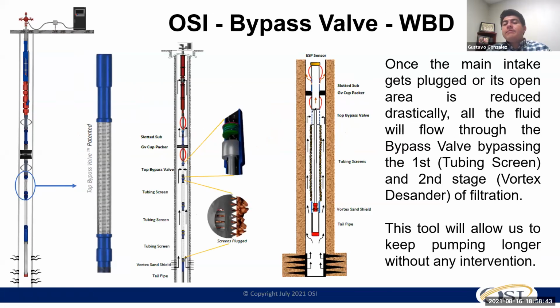So going back, it's worth selecting the sand screen as a method, as I mentioned previously. There is always that concern that filters or the screens plug. And yes, that's possible, that could happen. The probability is really high if they don't do a good job selecting the opening of the screen and understanding how the sand is actually behaving in your well. So this tool, this bypass valve, is designed to give that additional alternative in case the sand screen is plugged.